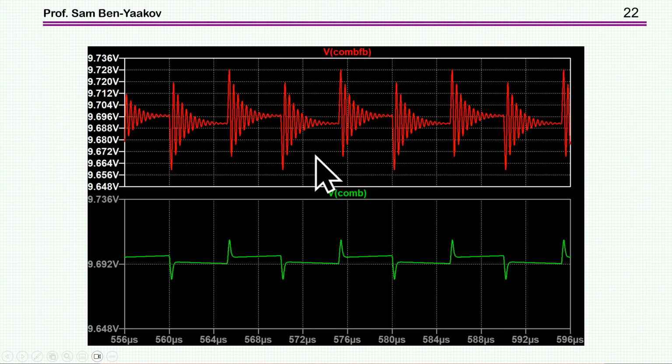You see, you got now oscillation, while without the bead, you don't have the oscillation, you have a spike here. Now, why is this oscillation? Because you have an inductive behavior of the ferrite bead with the 0.1 capacitor. It's now causing an oscillation. The Q is very low because you have low resistances there.